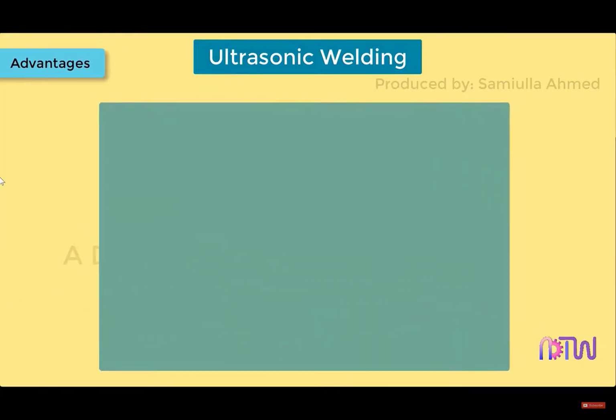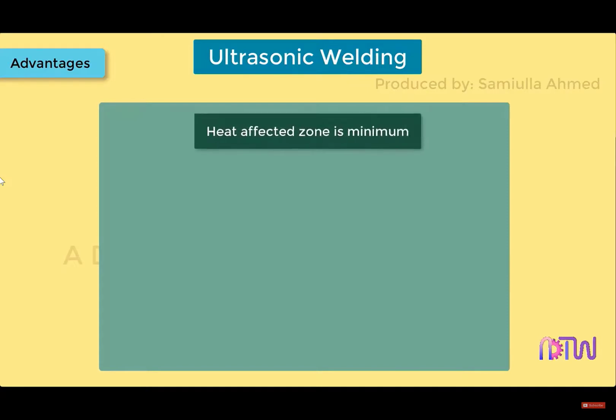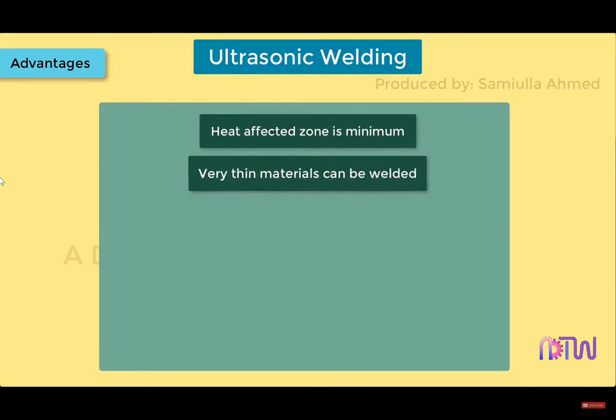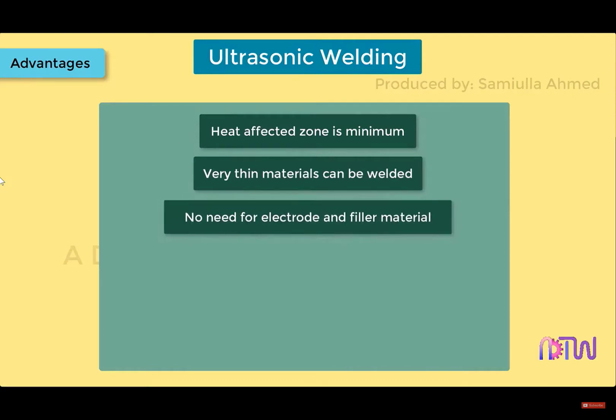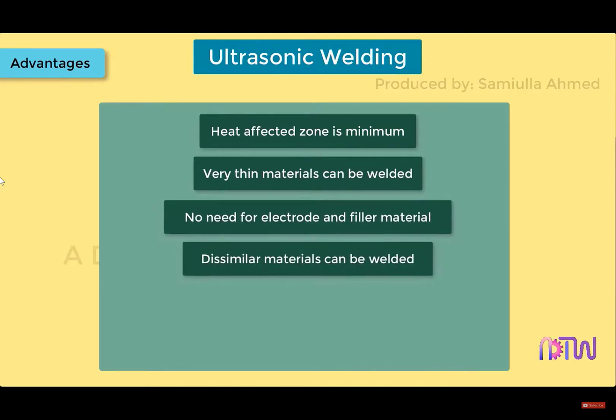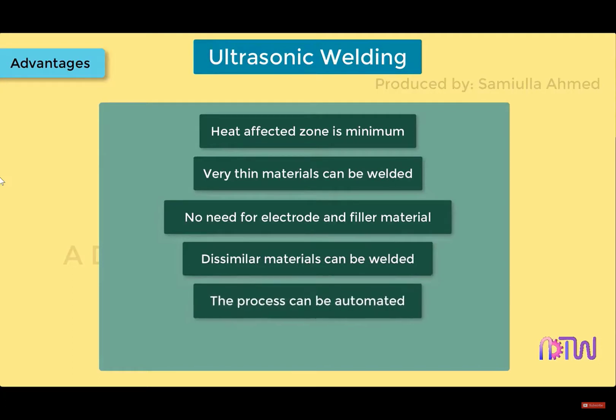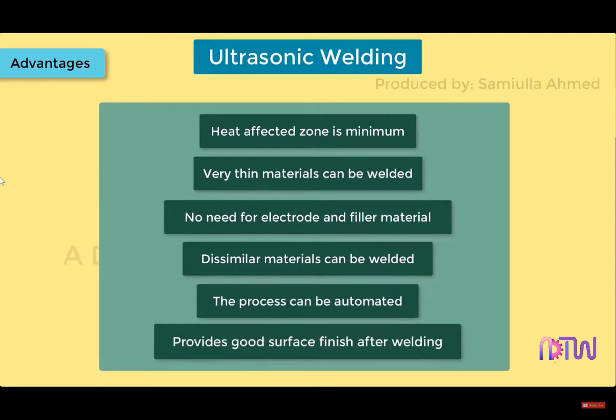Advantages: since no heat is supplied and no melting occurs, the heat affected zone is minimum. Very thin materials can be welded. No need for electrode and filler material. Dissimilar materials can be welded. The process can be automated. Provides good surface finish after welding.